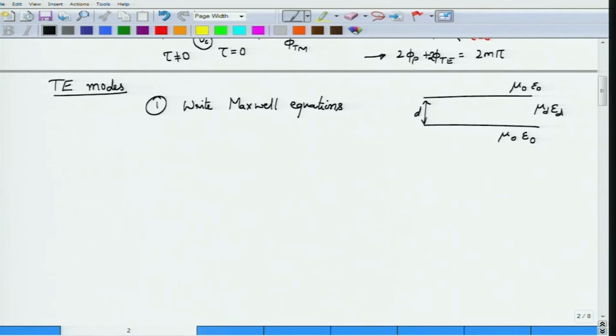We also of course need to pick a particular coordinate system. So, let us whimsically pick z as the direction of propagation. Okay. The slab extends along x to a large length, essentially meaning that the waves would be independent of x, because we assume that the length of the waveguide is so large compared to x that there is essentially no variation of the waves inside x.